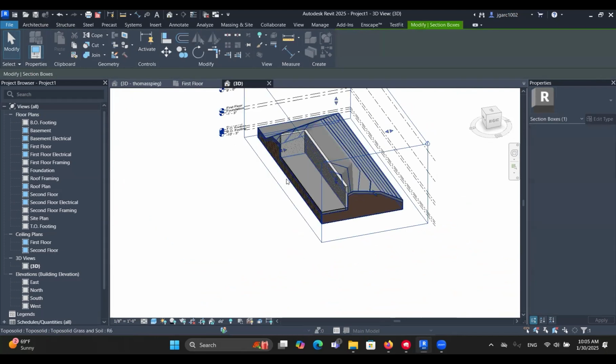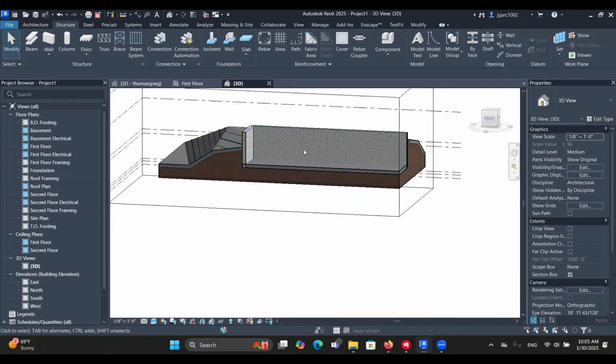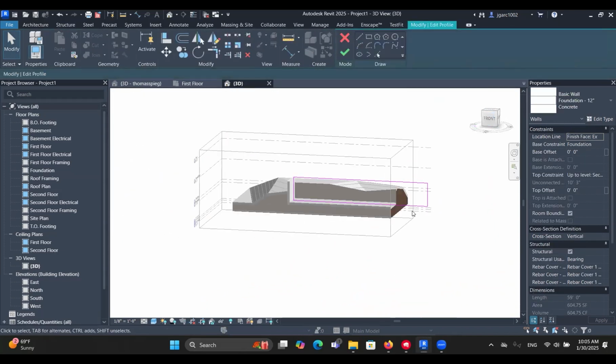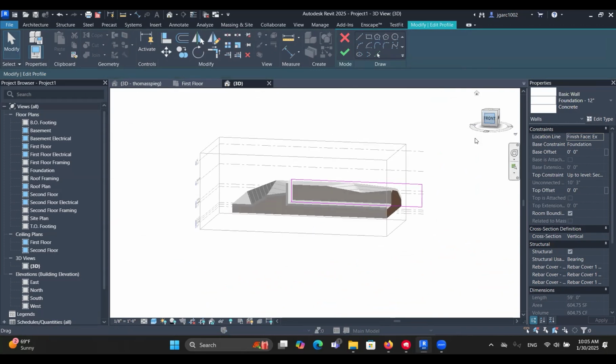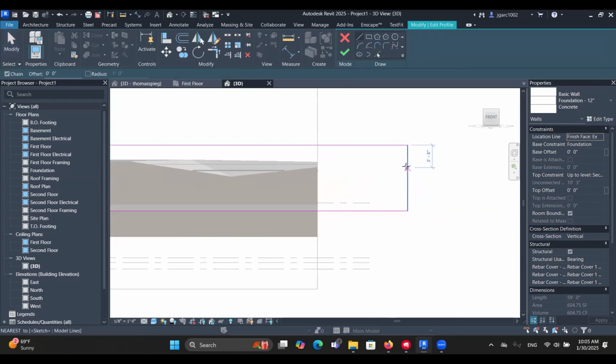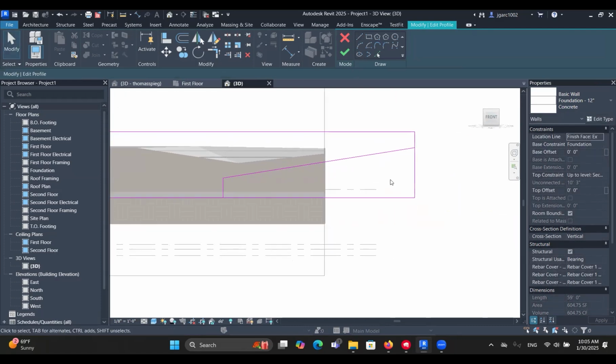Say for some reason your wall needs to have an opening, an angled opening, and it's not really going to be glazing, but it's just an opening because you want it to look nice. You just double click the wall and it's going to open up the boundary of the wall. You're going to go to the view that most favors this, and then you're just going to click whatever you want the opening. Say you want the opening here, you want it to do something like this.